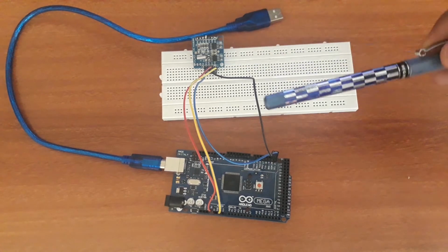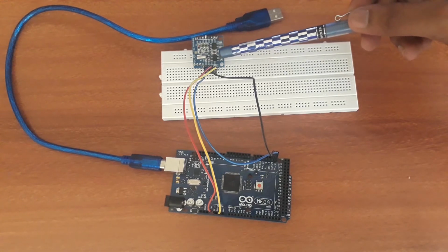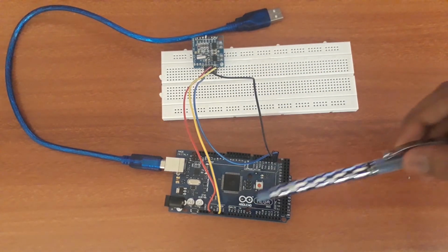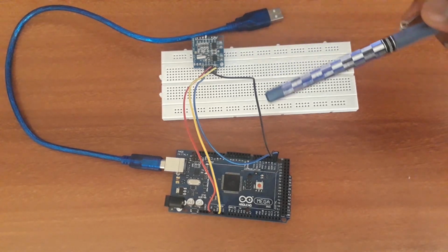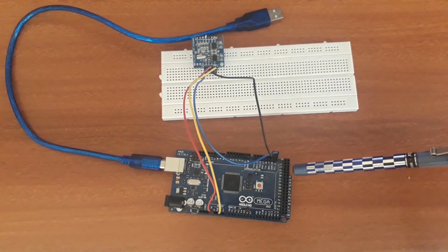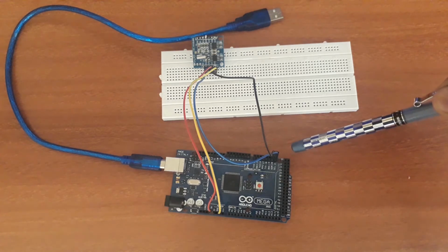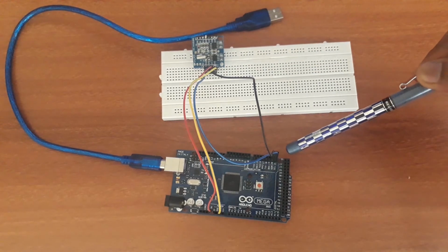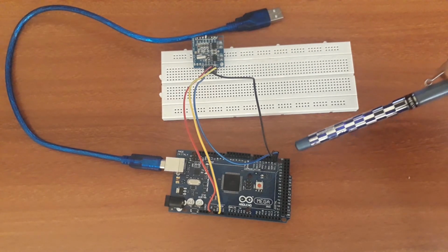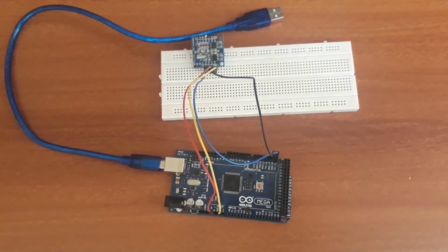That ground pin I connected with the help of a yellow wire to the ground. The positive VCC with the help of a red wire connected to positive VCC. You can check the SDA pin, with the help of a black wire I connected with the SDA pin in Arduino Mega. The separate pin is there, pin number 20, and the SCL pin I connected with pin number 21. Again the separate pin is there. Then I connected the SCL pin. This manner I made all the connections.